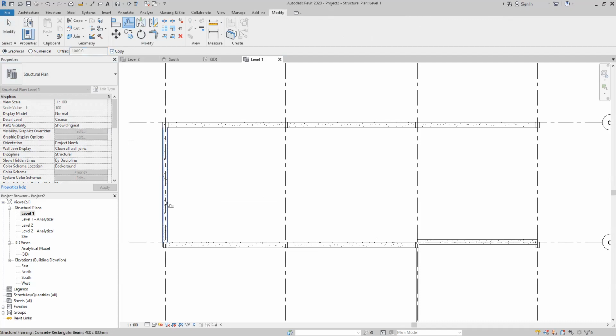Let's say graphical. So I select this beam and I offset it. Now you can offset any distance, so you can choose it. Actually, you can type on the keyboard 4 meters or 6 meters. Let's say my requirement is 6 meters. If you click numerical and fix 6 meters, then when you click here,